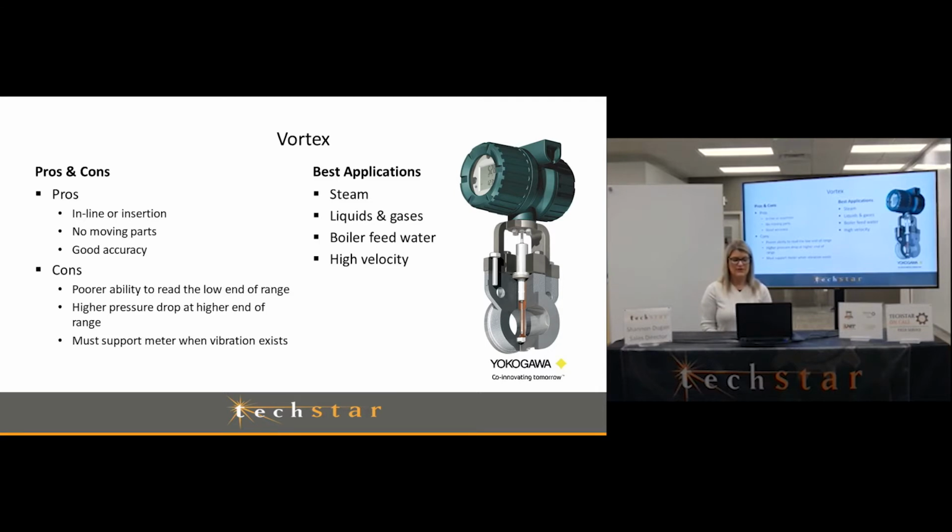These are very good for steam applications. A lot of them will have steam tables built into the transmitters, so it's a very cost-effective measurement for steam. It can do both liquids and gases effectively, boiler feed water, and things that are high velocity. So it's a very flexible flow meter.